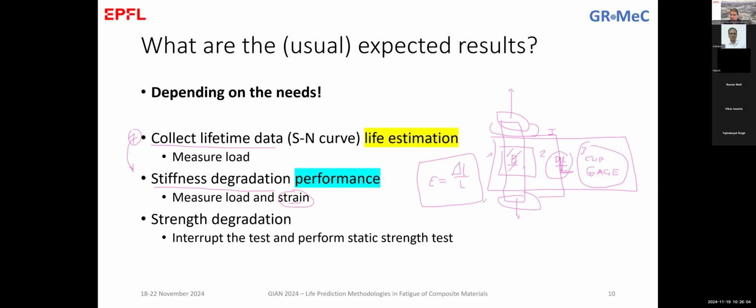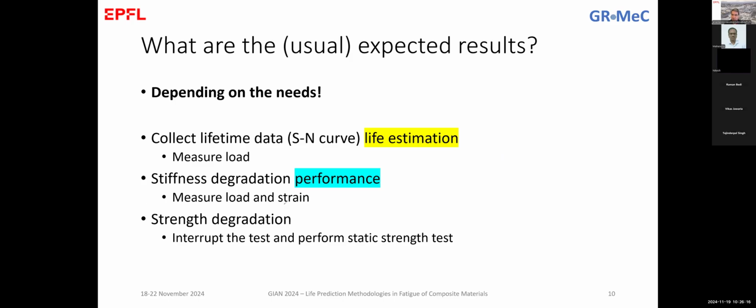So we can simply measure the strain like that, by measuring the displacement of the machine, which is also given by the machine while doing the testing. The problem with these strain measurements is that sometimes we have slippage in the grips of the machine, and the machine may not be stiff enough to test the specimen. In these cases, the strain that we measure from the machine displacement is usually larger than the actual strain on the specimen.